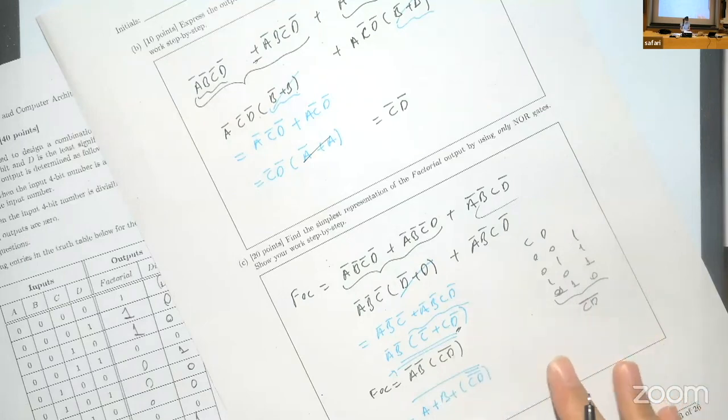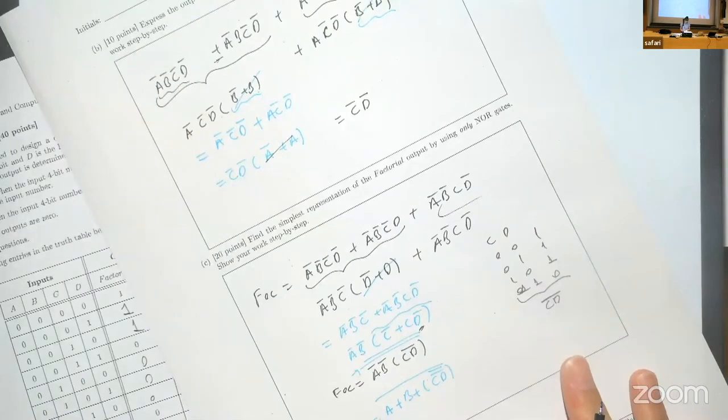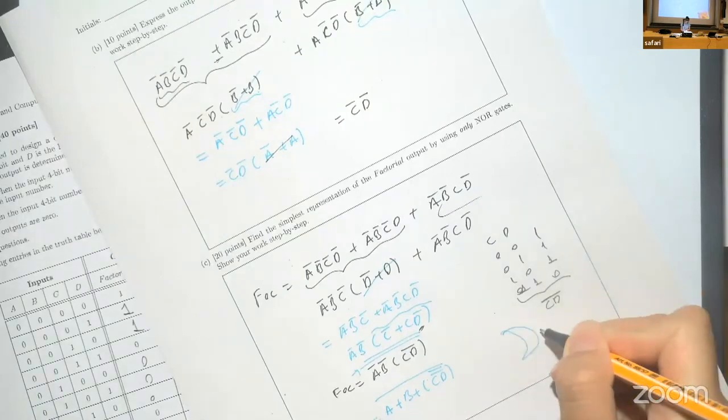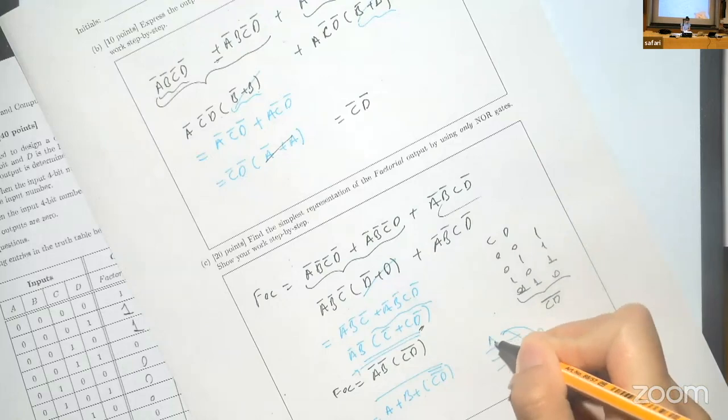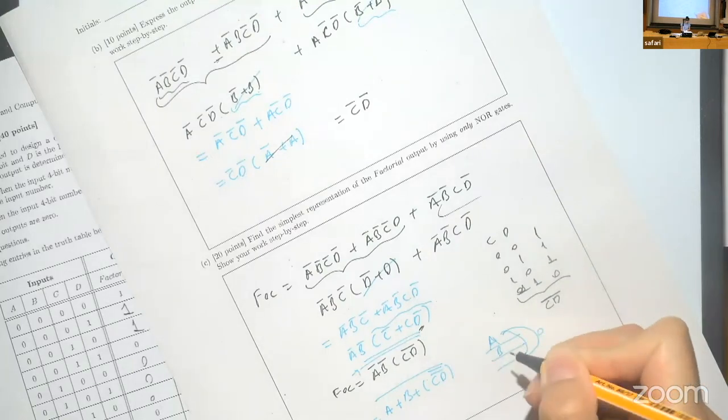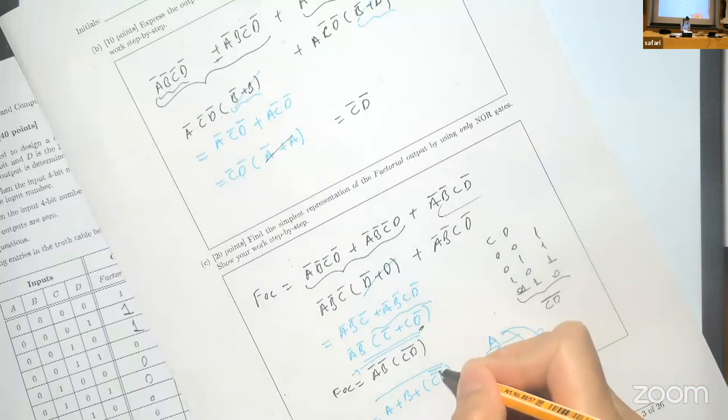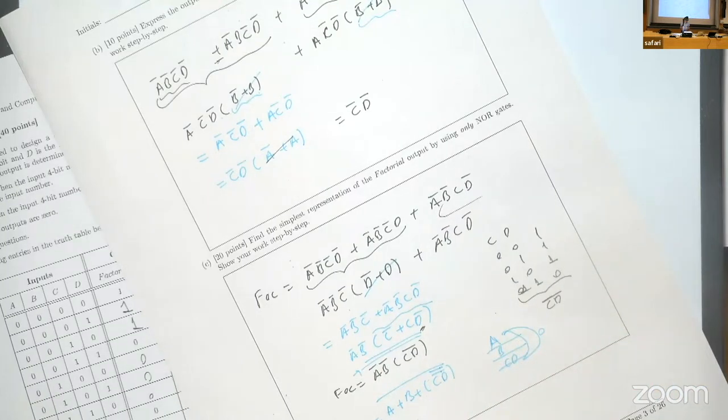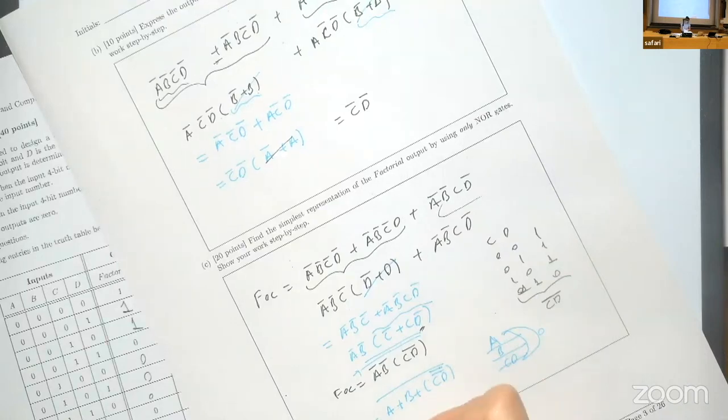Now we have almost everything in the NOR gate form. So if we have a NOR gate, we have 3 inputs now. The first one is A, the second one is B, and then the other one is CD. Because if you negate something 2 times, you will get the original thing. But the thing is, CD is not in the NOR gate form. So we need to figure out how to express CD in the NOR gate form. And CD is equal to CD negated twice. We just use the same thing, which is equal to C naught or D naught.